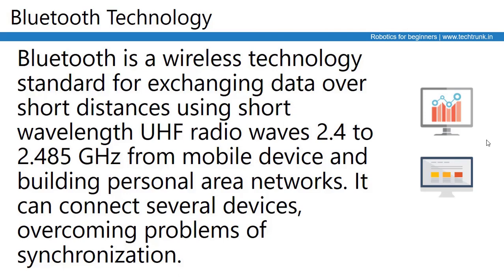There are two modes of a Bluetooth module. One mode is master mode and the other mode is slave mode. If the Bluetooth module chooses which device to connect to and chooses when to send data and when to receive data, the mode of the Bluetooth module is master mode. In case the Bluetooth device allows other devices to connect to it by pairing with the password allotted by the module, then the module is in slave mode.